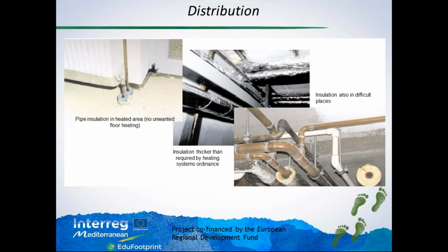There are also some particular cases where two buildings are both supplied by the same boiler, and sometimes the distribution pipes are going outside before going again into the building. And if those weak points are not very well designed, the possibility to have very big losses is very high.